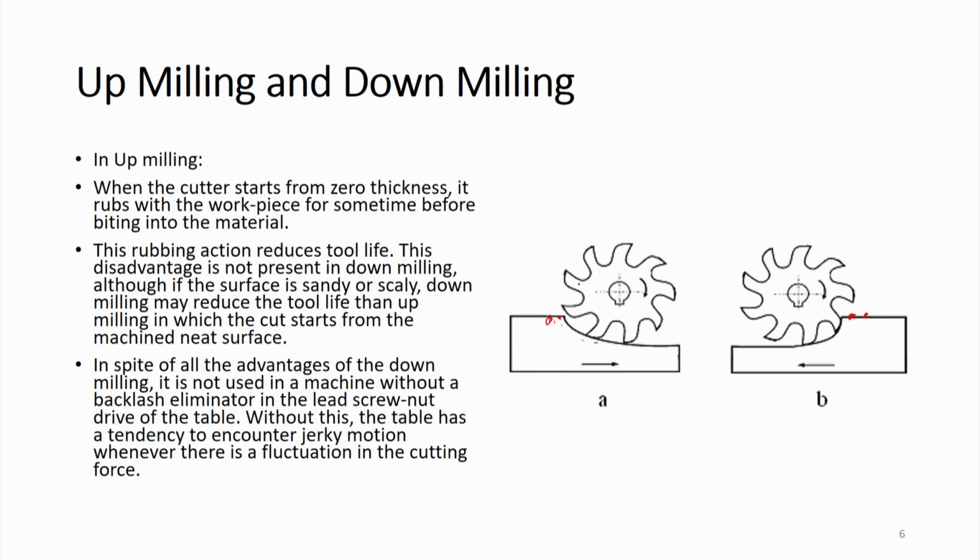So, that problem is not there. So, tool life on a sandy surface will be less in down milling, but otherwise in general down milling will provide more life.